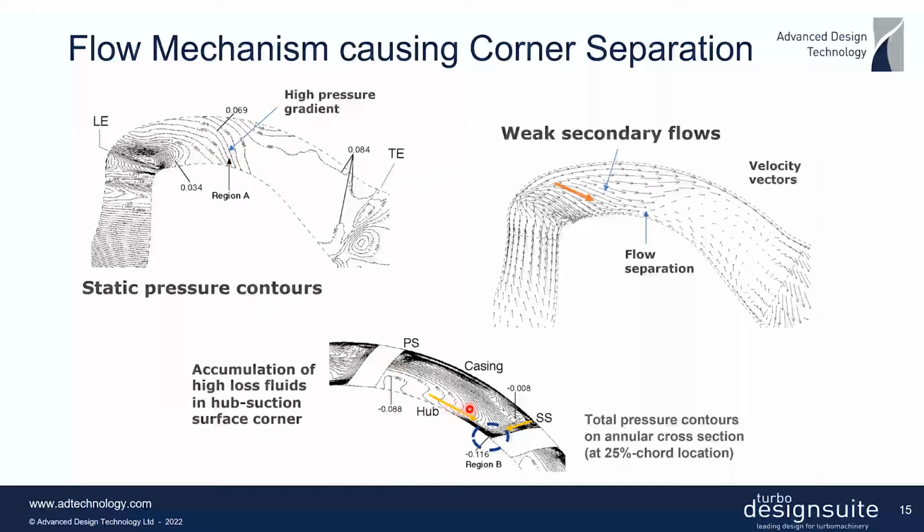Now, although there is a correspondence, positive pressure gradient alone does not actually result in a big corner separation. It could result in a simple separation bubble, but not this sort of tornado type separation that we are observing here. So there must be something else happening, and so the stagnation pressure contours were plotted, which we see here at the bottom of the slide, just before the separation.